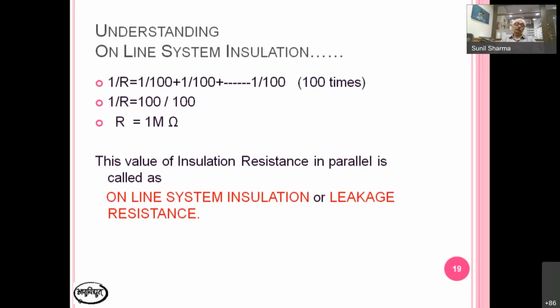Your cable is okay, but maybe your system is not okay, because the system has three or four things: power supply, K-rack plus these cables plus load, etc. So leakage can be anywhere, and this can give you trouble. I think everybody understood the difference between the insulation you have measured with a Megger and the leakage resistance measured by the ELD.